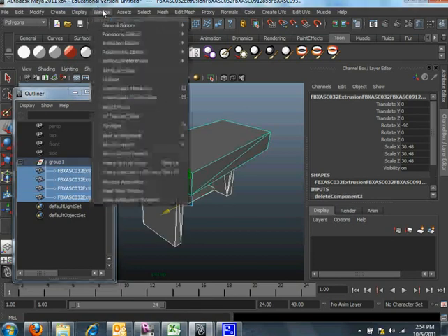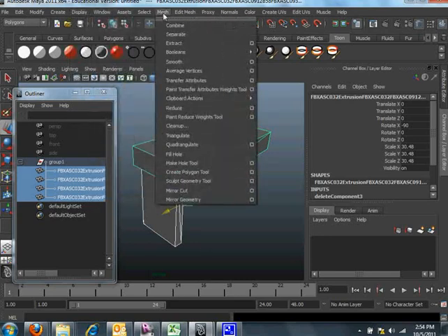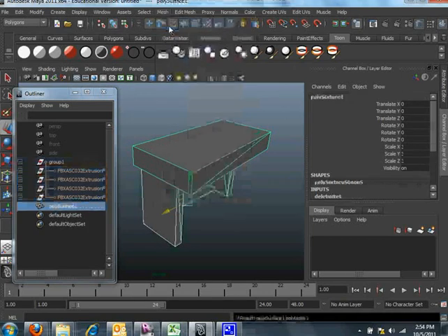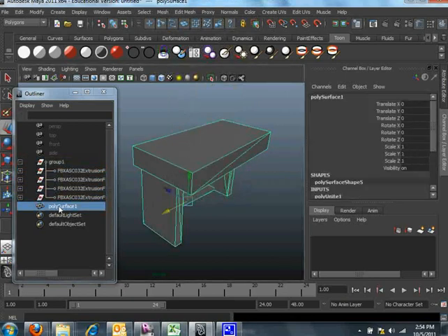So I will use a command. The name is Combine, which is available in Mesh. Combine here. Okay. So it's kind of like group, kind of like a union in the Boolean operation, but it's actually easier. It doesn't calculate the intersections. It just merges everything as one single object. So here we go. You merge as one. If I select, you see this is one single object. All right.